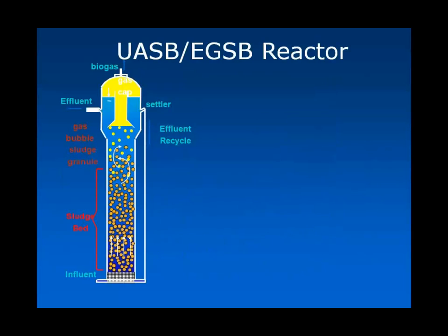You've got the granules that are growing, you have some mixing happening, you have some gas release, you have some solid separation, and everything kind of going on together there at the same time. So if we were going to put one together, we felt that we needed to have a reaction model, obviously, to do the anaerobic treatment.